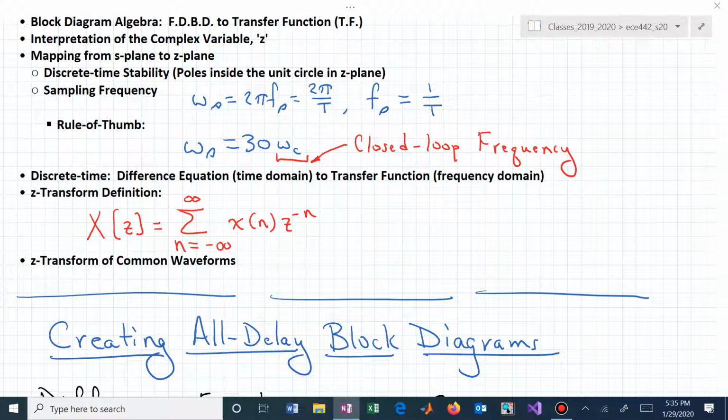Then we will get into going from a difference equation into a frequency domain representation by this operation of z to the minus 1, or their powers of z to the minus 1, and that naturally leads us into, can we find a z transform, relative to how you've now found a Laplace transform? How do we take this sequence of numbers that we are representing as little x of n in this expression, and create a frequency domain transform representation of that time sequence of numbers? And that's the z transform.